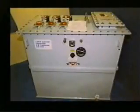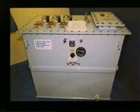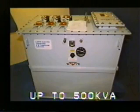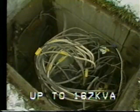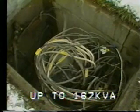The commercial subsurface transformer is usually 3-phase and manufactured in sizes up to 500 kVA. The residential subsurface transformer is usually single-phase and comes in sizes up to 167 kVA, that is 1/3 the size of the largest commercial unit.